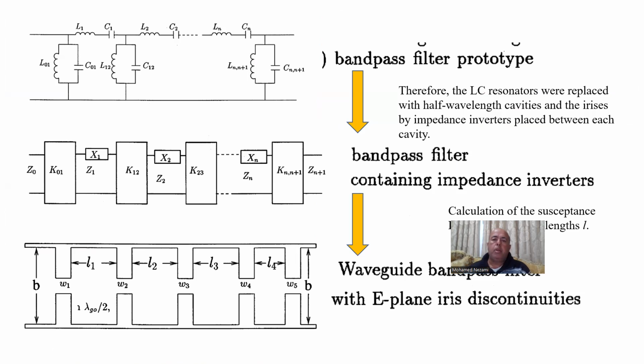I'm assuming that you have already gone through this situation where you have a filter wizard designer that you enter the center frequency, the bandwidth, the rejection requirements, the insertion loss requirements, the input and output return loss, the group delay, whatever, and then you basically come up with the dimensions of the waveguide filter parameters, which in this case are the iris dimensions, the width of the iris itself, the length, and then the placement, the distance between them, which are shown in this case.